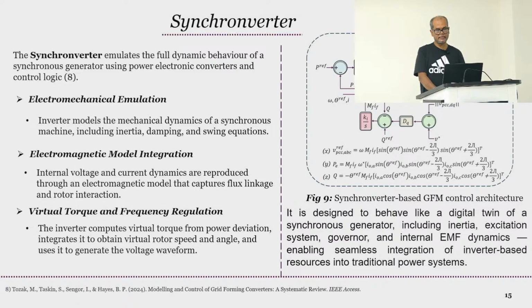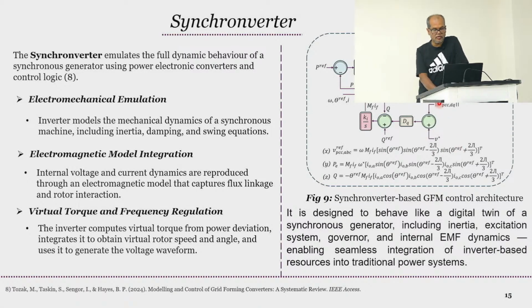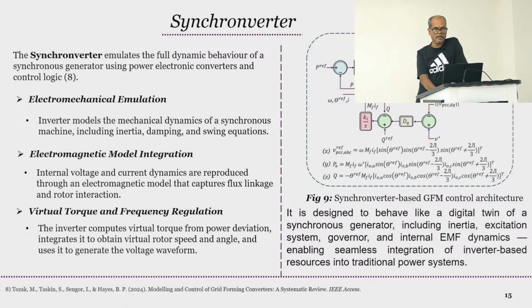So the inertia comes in here, along with all the voltage equations you're going to be solving, and at the end you get the power. It is a little bit complex, but it's not that you cannot do it. You just need to first think about what sort of synchronous machine model you're going to use, then based on that write those equations, and from that find the power.